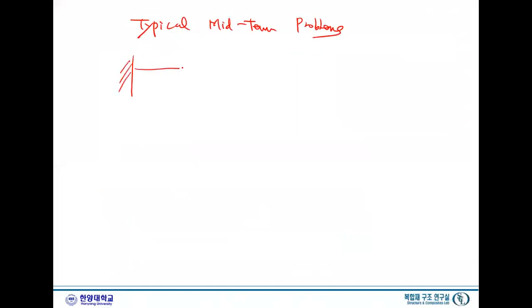Say we have a beam, and what we derived was, given L and given EI and under the moment, how much it rotates, right? But let's say we have another beam attached which has a different bending stiffness. So E1, I1, and L1, and this one is E2, I2, and L2, and then we apply a moment. Now, what we would like to find is how much this guy rotates.